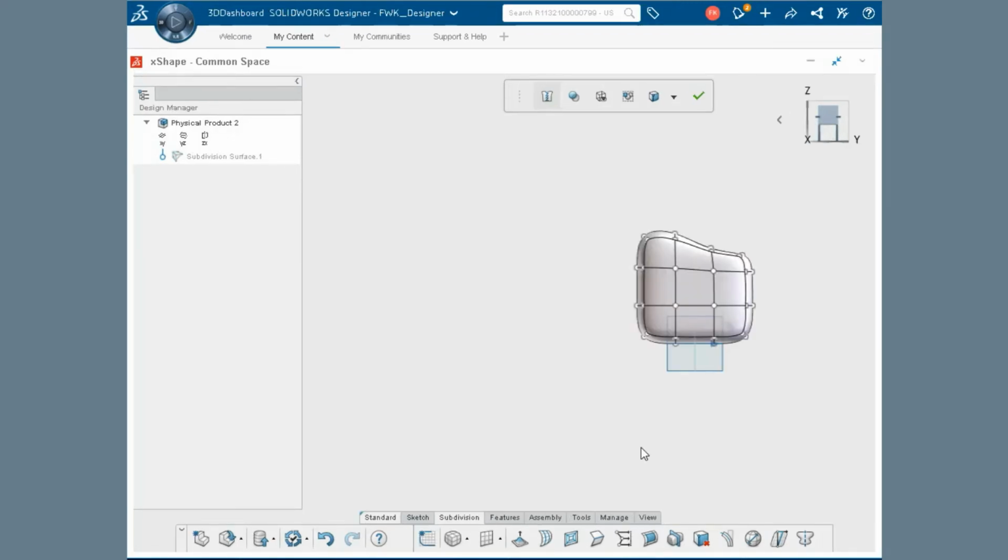How about selecting a large amount of elements? The best way to do this is to use box selection. Change the view orientation to an orthographic view like front, top, or right. Use box select to select a group of vertices. Note that even when you select faces, you're really selecting the vertices of those faces. This is also where the Select Only Visible Elements option comes into play. It is off by default, so all the elements through the model are selected by the box.